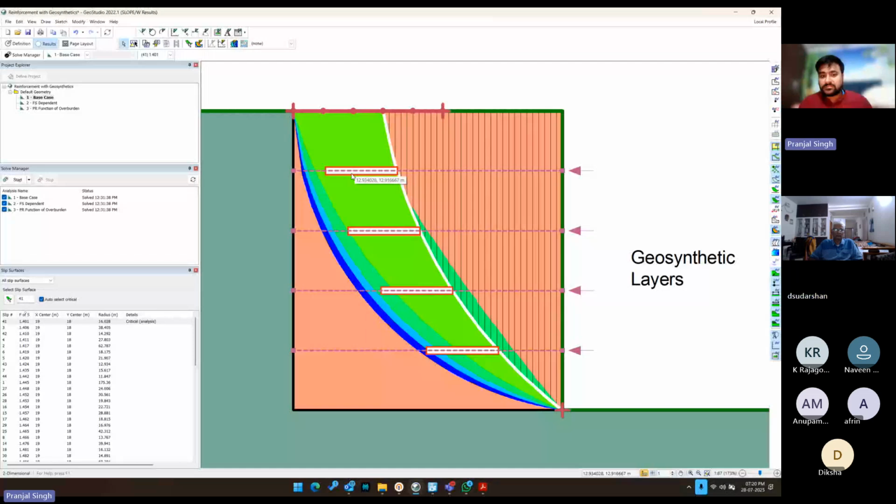And so this represents how much embedment length of the geogrid is actually required. Since we have provided an embedment length greater than this, there won't be any issue. This geogrid will fail in tension rather than in embedment. So here, if you look at the properties of this geogrid, we have taken a pull-out resistance of 75 kPa per unit area. So this value is constant.